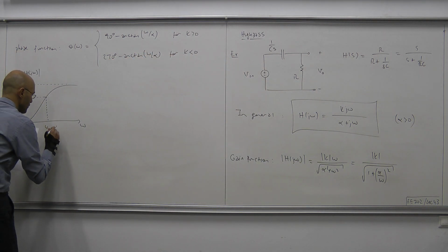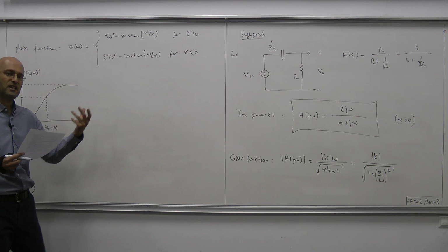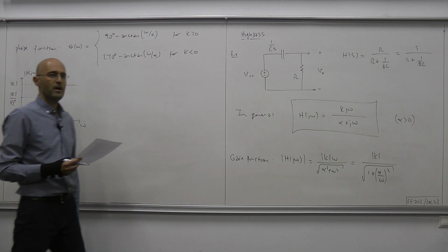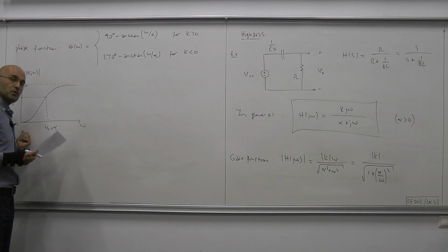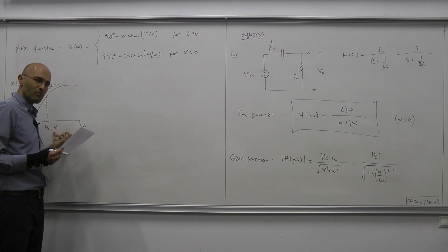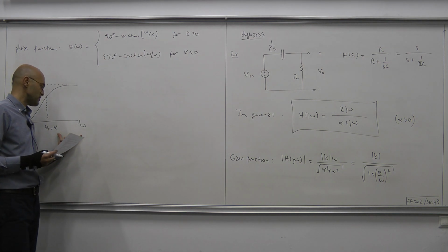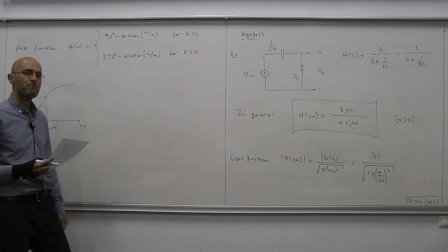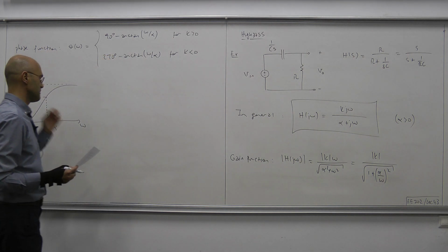Okay, so omega c therefore equals alpha. And once you have the cutoff frequency, you immediately have the pass band, stop band, and also the bandwidth. This is the stop band, the frequencies from 0 to alpha. Frequencies larger than alpha make our pass band, and the length of the pass band, which in this case is infinity, makes the bandwidth of our high pass filter.